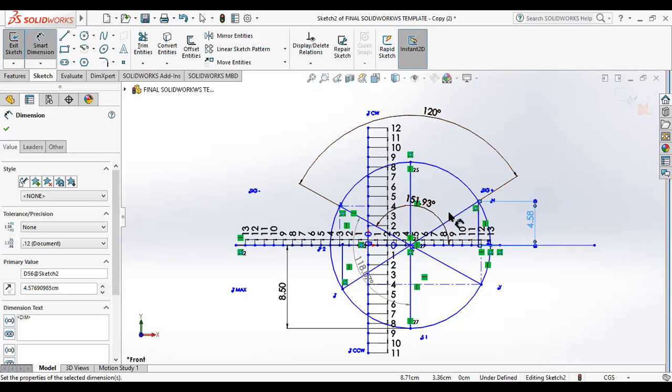It is theta p1. Since this is measured in the clockwise sense, to arrive at theta p1, that is sigma p1, this will be minus 75 point something, and theta p2 will be plus of that, minus 75 point something plus 90, whatever it comes to, will be theta p2. Now, in order to measure the tau max, from the center point, draw a vertical line meeting the Mohr circle. This is the radius. This is tau max or tau minimum.